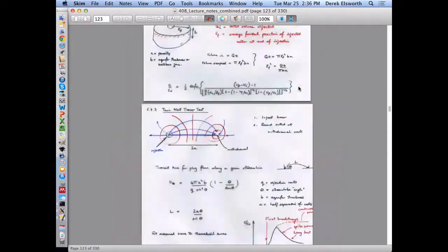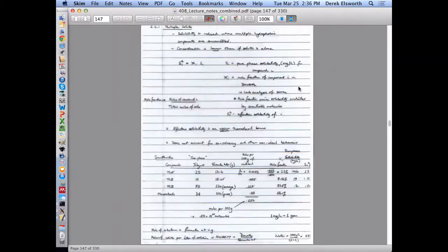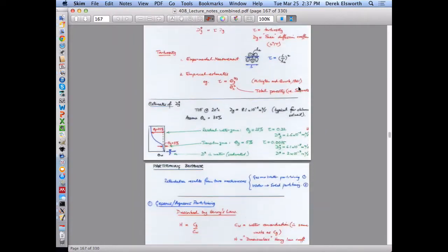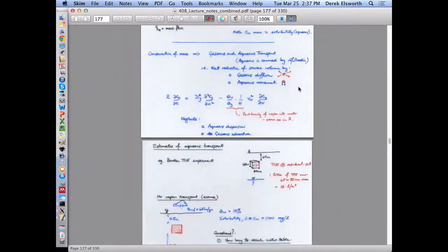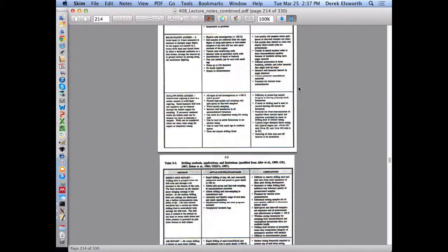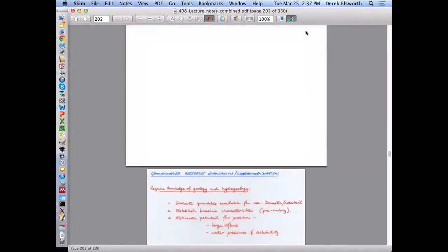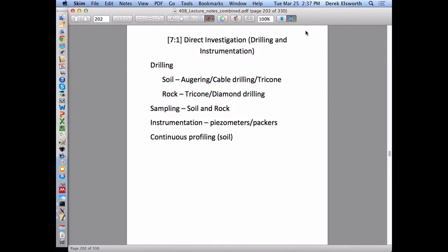So we've made this big picture point that if you have the stratigraphy and the information that you've used for Smithville, for instance, you don't get that for nothing, and so you have to physically acquire that. The methods of acquiring that are through direct site investigation, drilling and sampling, drilling to be able to figure out what the stratigraphy looks like if you use a borehole camera, but also sampling in that profile to be able to look at stratigraphy.